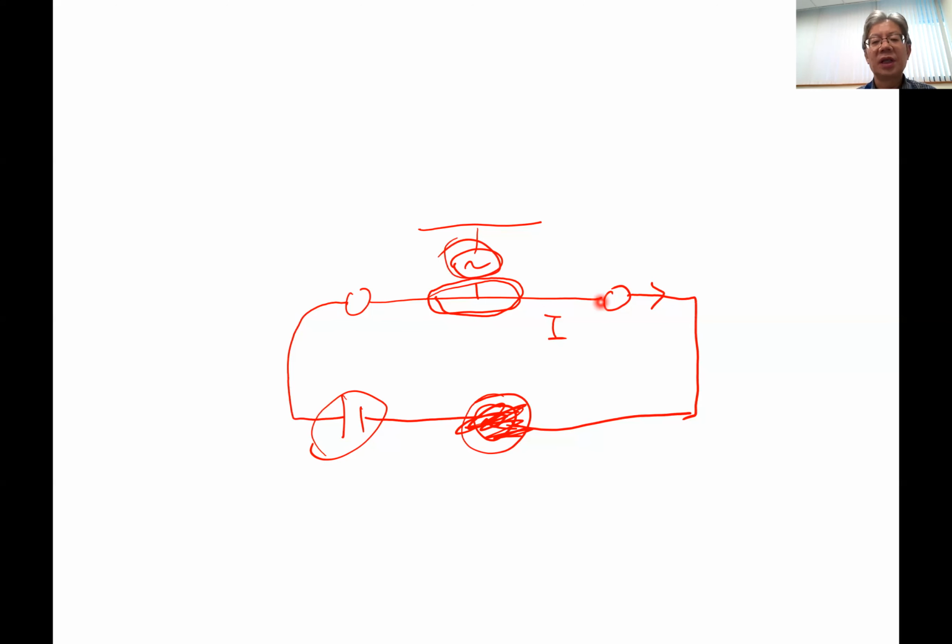And then of course, you get amplification. Why? Because eventually the current flowing through this path will change proportionally to your signal. But the overall current in this branch or path of the circuit is much, much larger than that in this control terminal, right? So that's the reason why a three-terminal device is suitable as an amplifier, right?